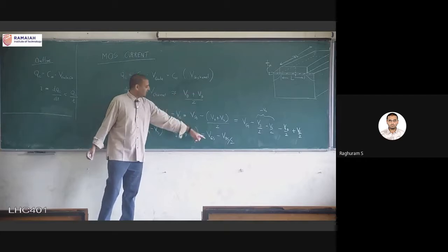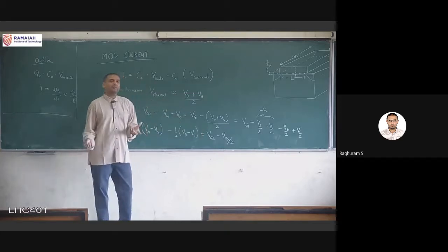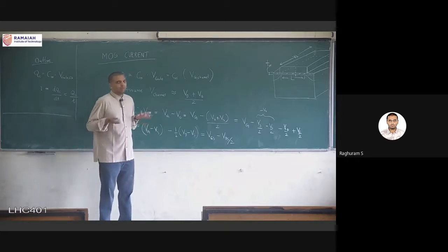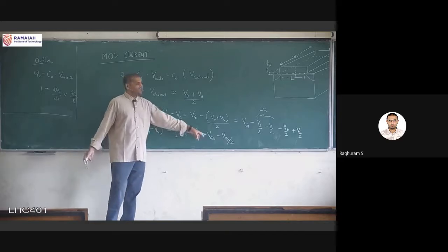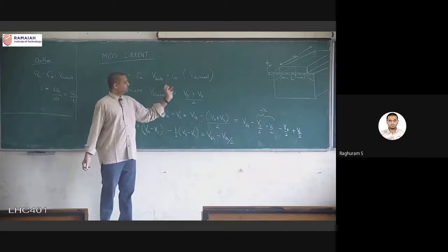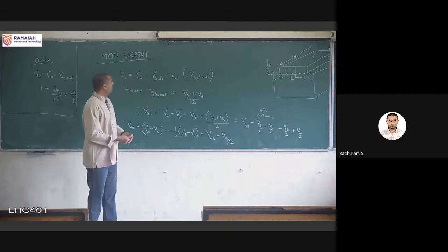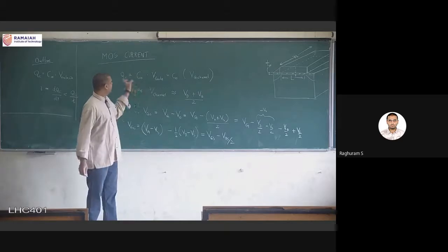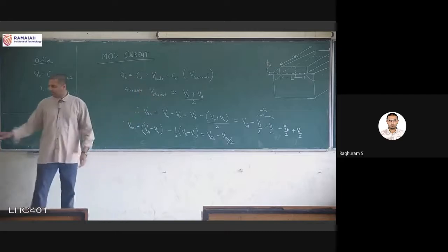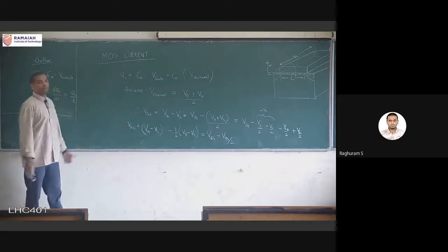Now this is very nice because this is in terms of our terminal voltages. Our transistor's three terminals are gate, source, drain, so all those things I can measure. Once I measure them, I will be able to get all these numbers. So that is why this last expression is very nice, and this is the one we will use. This is the first part of the derivation, which calculates the channel charge. Now for the second part, where we are applying dq by dt.